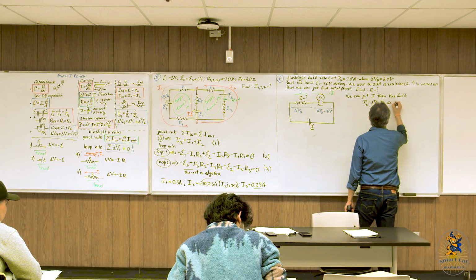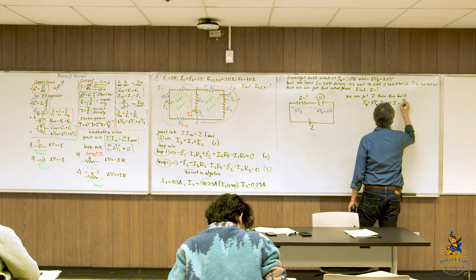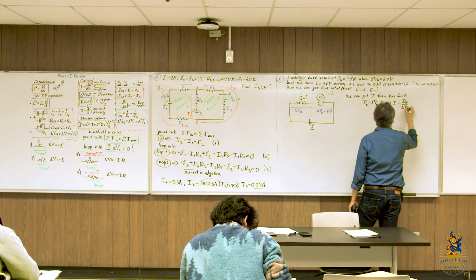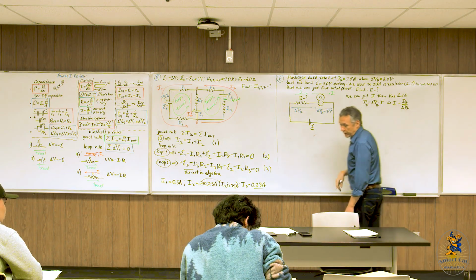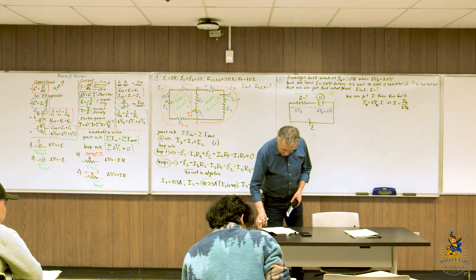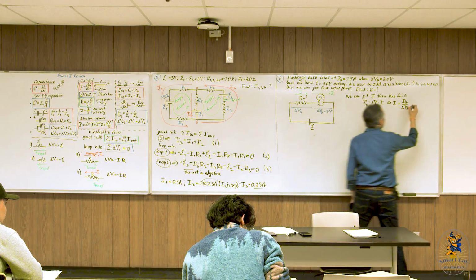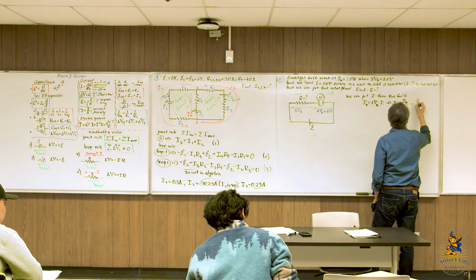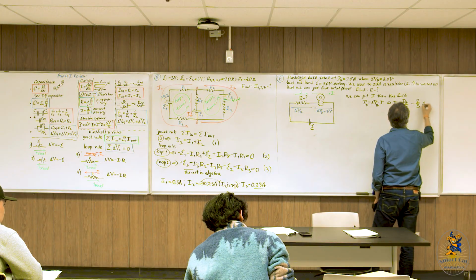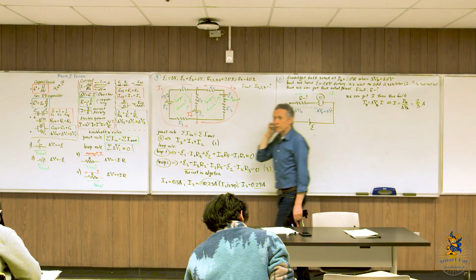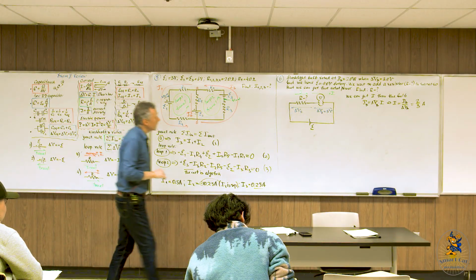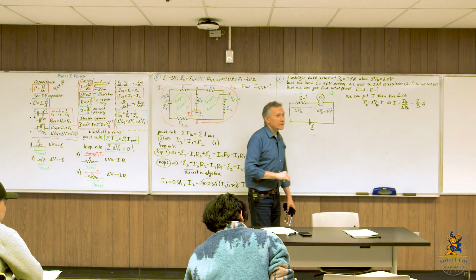From here, current will equal the power divided by the potential difference across the bulb. Of course you can plug in numbers. Power is 2 divided by 3, so 2/3 amps. So that should be the current if we want to satisfy these conditions. Great, so now next step.